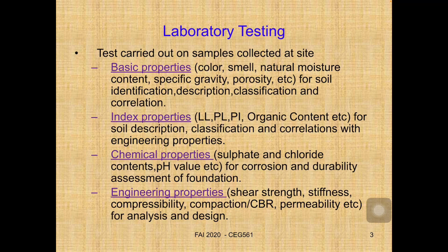you need to use the values with the empirical equation, or you have to calculate, let's say, the bearing capacity, which you will learn in the next chapter, chapter 2, or whatever design, slope design or retaining wall, you need the shear strength properties, which is C and phi, and also the stiffness of the soil as well.